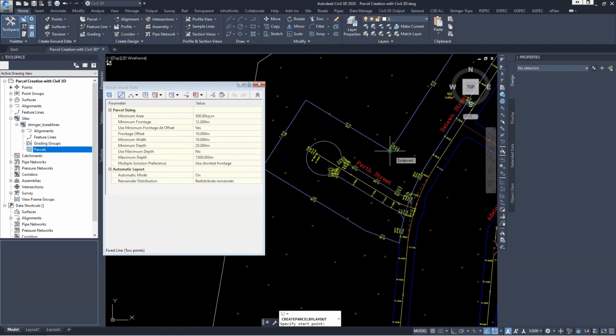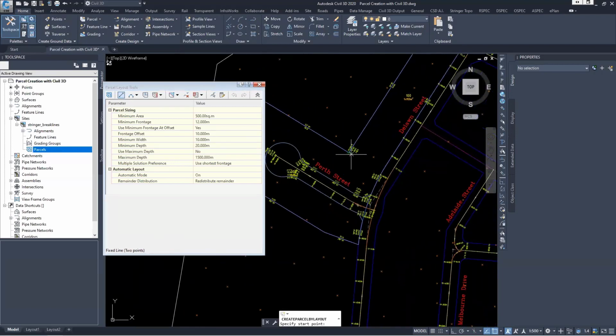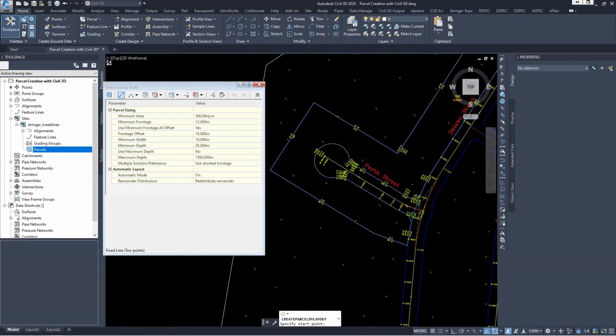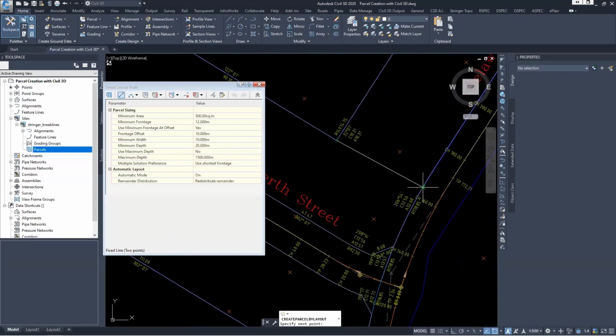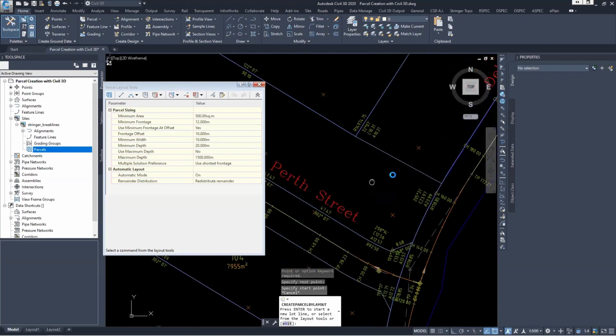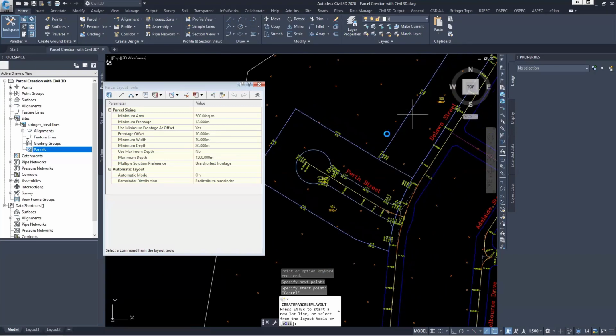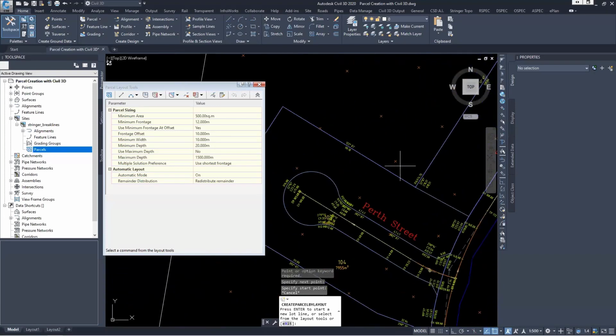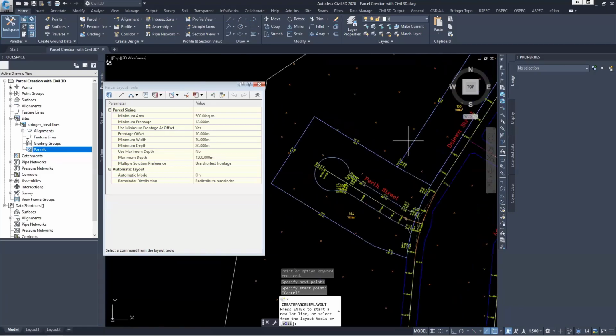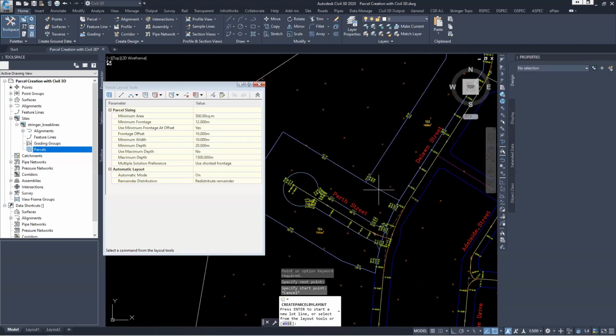And now it's simply selecting which points I want to use. So I want to turn this into more of a rectangle-like block. So I'm just going to select this point here. Since I have perimeter, do perpendicular to make that straight. And you'll see I now have another lot here and another lot here. So it's split it automatically through the use of the site that we've assigned it to. It's recognized that these are under the same site. It's being split by a closed polyline. I'm going to turn this into 2 separate parcels. It's a really nice tool for automatically getting all that done.